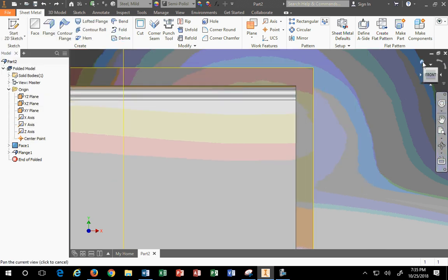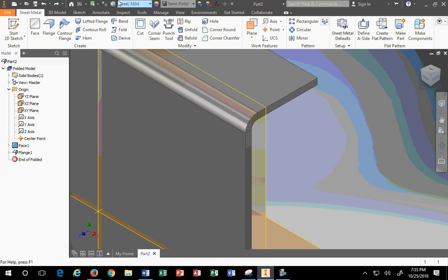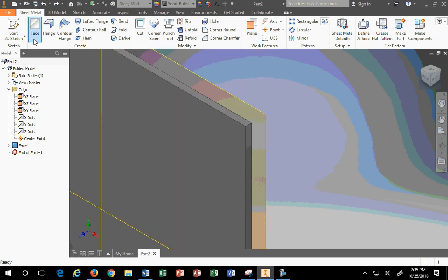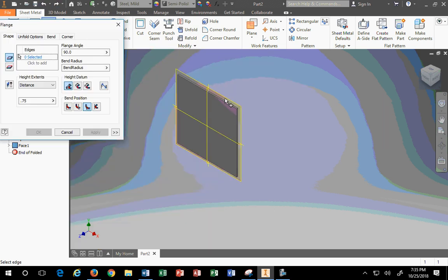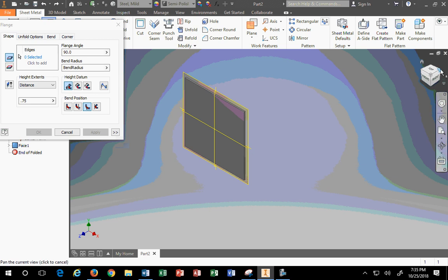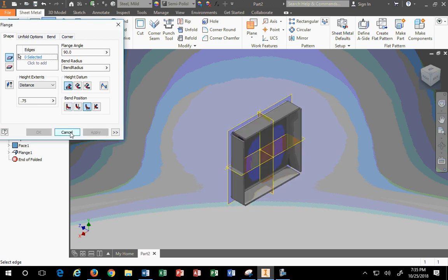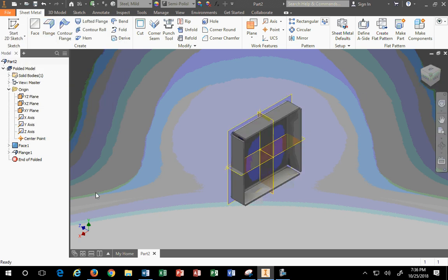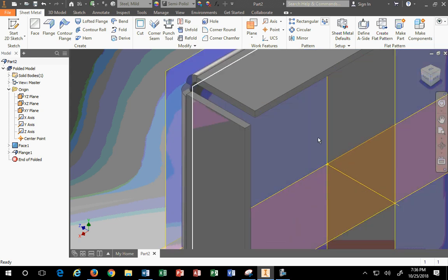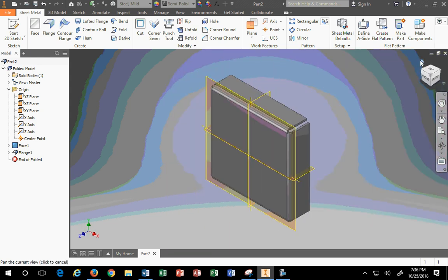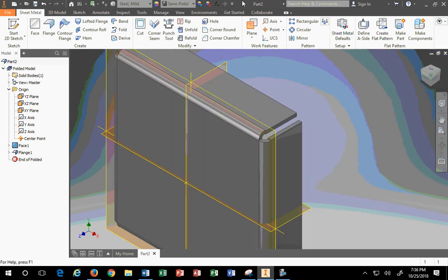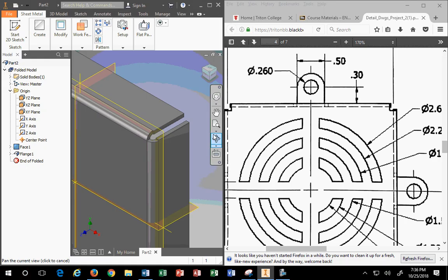I'd want as narrow a seam as possible so I can minimize the amount of welding, and then of course the complementary grinding that goes with welding to clean up the corners. Those are horrible corners to weld. Never want that. Okay? So next is, but this part doesn't look like it's welded.